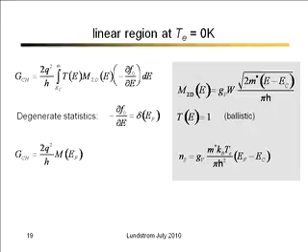So transmission is 1, and I just get the conductance is 2q squared over h times the number of channels. That's a very common expression that people discuss for the quantized conductance. You can see that at T equals 0. In the previous slide, I worked it out for Maxwell-Boltzmann statistics. In general, in MOSFETs, you're somewhere in between, depending on what the gate voltage is.